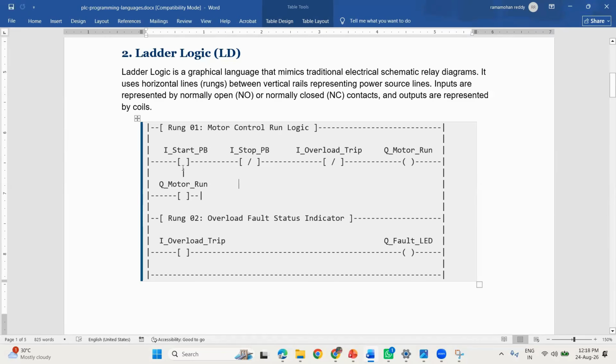So this is a push button, and if you remove the push button, there won't be any current flowing there. So this status is taken here, motor run status. So if you remove the push button switch, the current flows through this one, and so the motor will remain in on condition even if this push button is removed.